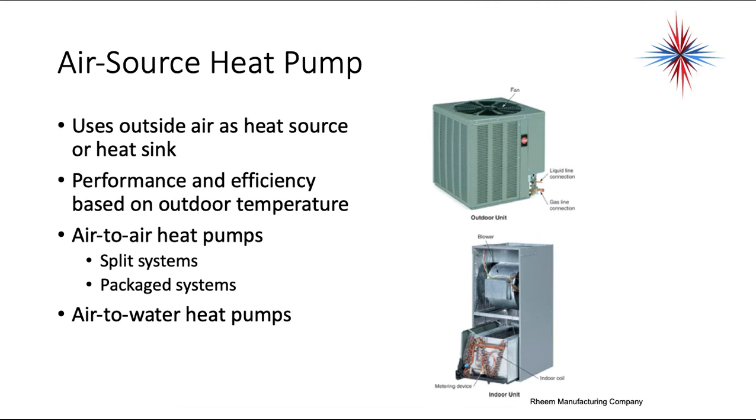The air source heat pump uses outdoor air as a heat source or heat sink. The performance and efficiency are based 100% on the outdoor air temperature. Air-to-air heat pumps are extremely frequent as split systems and package systems. The other type of heat pump is an air-to-water heat pump.